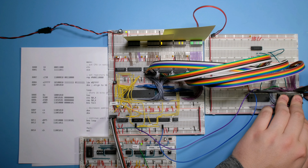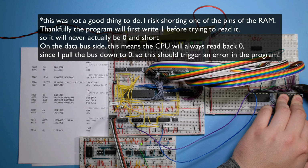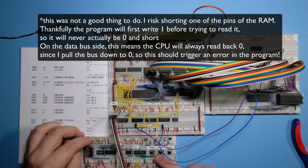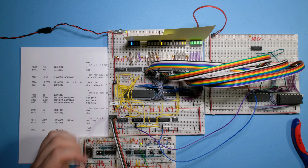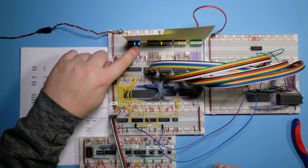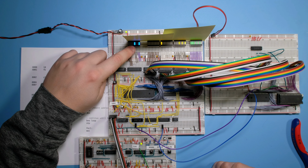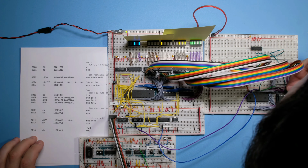So I'm going to take one of the data bus lines of the RAM, and I'm going to force it high. So it's always 1. Let's now run the program and see if it detects a problem, just to make sure. There we go. So it's running now. And yes, this is the wait LED, and this is ready, being pulled low. So as you can see, the CPU is now waiting, so it has detected a problem here.